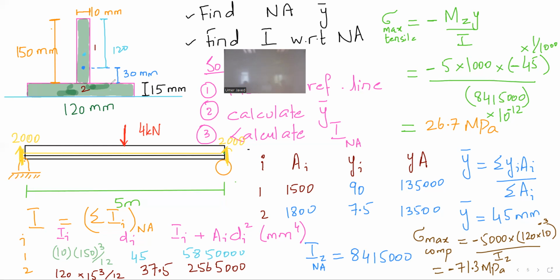One minute. Look, the question says the shearing stress at point D which lies on a 15 millimeter radius. So part B is done. Do you want me to tell you part C? Yes, sir. Part B is done. Okay, part C says the percent of the torque carried by the portion of the cylinder within the 15 millimeter radius. Okay, this is the question. The percentage of the torque carried by the portion of cylinder within the 15 millimeter.